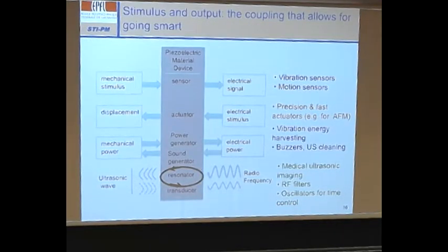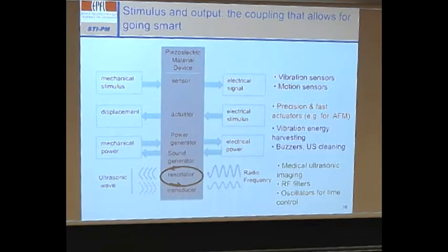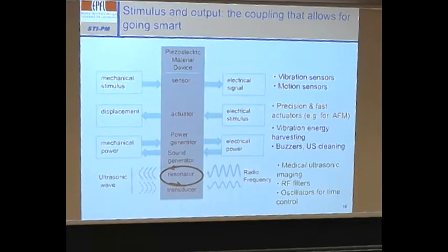Now, if you look at the whole picture of piezoelectric materials, we have, for instance, a mechanical stimulus making a sensor, and an electrical signal goes out. This is typically for vibration, sound sensors and motion sensors. We have the opposite direction: electrical stimulus and then displacement, precision and fast actuators. All atomic force microscopes are, in fact, actuated, either the tip or the substrate, by a PZT actuator.